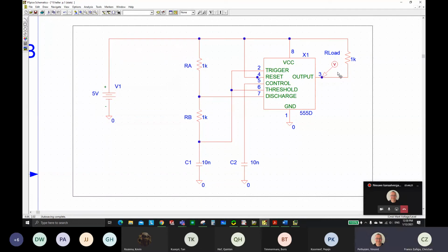If the temperature changes, then the value of the resistor changes. Just a little bit, but it changes. Maybe that 1K resistor is 1K at 21 degrees Celsius, but in the winter it freezes at night. It could be a few degrees below zero now, and next week I believe it could be -9 or -10. Then the value of that resistor changes. So that's something else that can change. It has a tolerance, the temperature tolerance of a component.